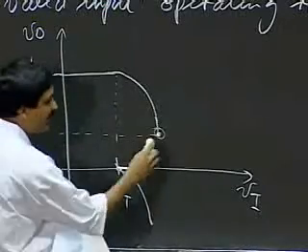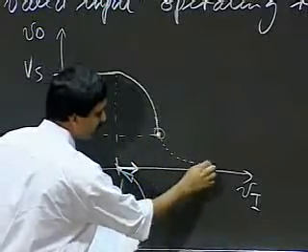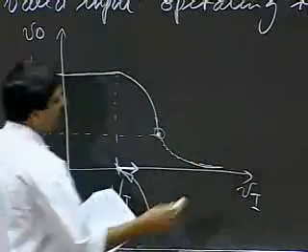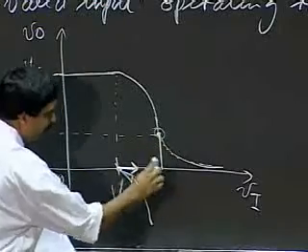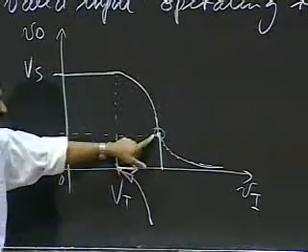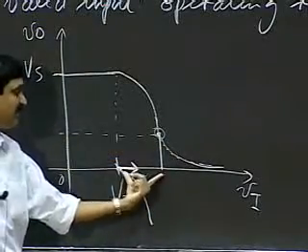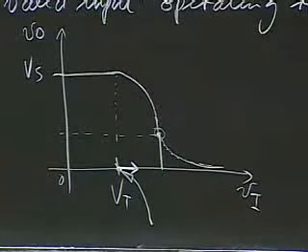Somewhere here, I go into my triode region and begin to show a different behavior than the amplifying square law relationship, going into my triode behavior. So I need to find out what this point is. Once I find that, this will be my valid operating range. So let's figure out what that point is.